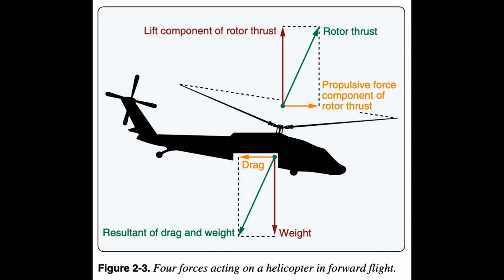As shown in Figure 2.3, if dynamic pressure is increased, the static pressure will decrease. Due to the design of the airfoil, the velocity of the air passing over the upper surface will be greater than that of the lower surface, leading to higher dynamic pressure on the upper surface than on the lower surface. The higher dynamic pressure on the upper surface lowers the static pressure on the upper surface. The static pressure on the bottom will now be greater than the static pressure on the top. The blade will experience an upward force.